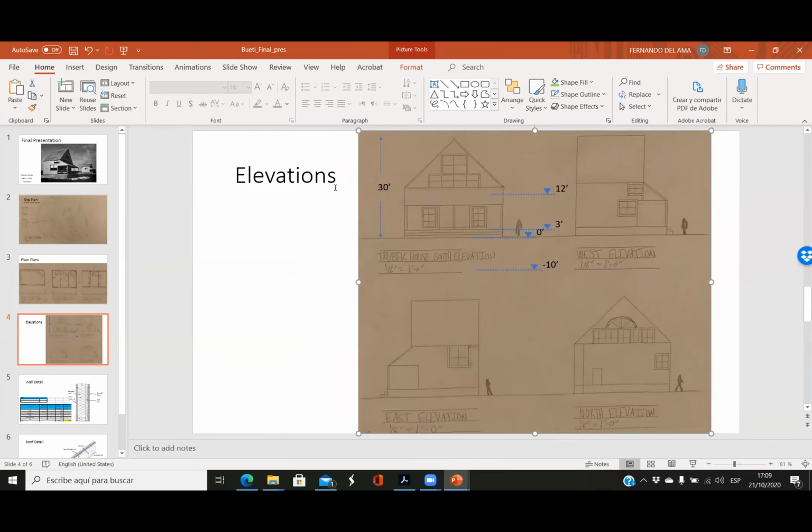Okay, but working with levels in sections and elevations helps a lot, and so we can understand not the height of the house, but the height of different levels and the floor. Yeah, and it's important we always have these levels where the floor is. Okay, so it's not the bottom of the slab, it's the top of the floor, of this floor.